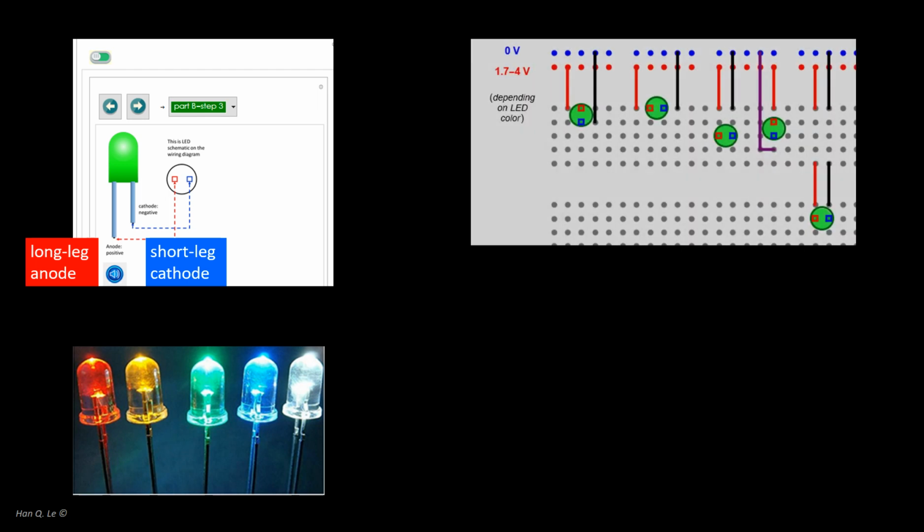For the first-time LED user, this is a helpful mental exercise. Which of the 5 LED breadboard wiring configurations as shown will work, that is, emit light? In fact, if all 5 are wired as shown, none of the LEDs will light up, and the power supply will indicate it is short-circuited. Do not do this with batteries at home, because batteries do not have a built-in short sensor to break the circuit.